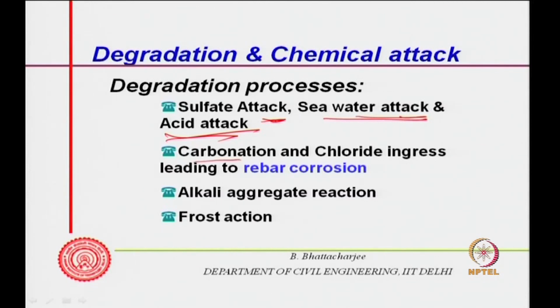These two, carbonation and chloride ingress, are not degradation processes for concrete per se, but they are a problem for reinforced concrete and pre-stressed concrete, because they can cause rebar, steel reinforcement corrosion. So, carbonation and chloride ingress lead to rebar corrosion.